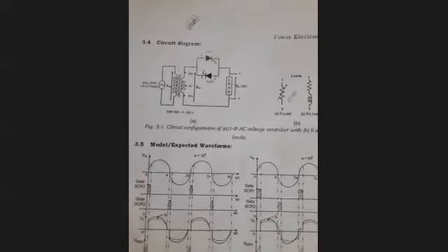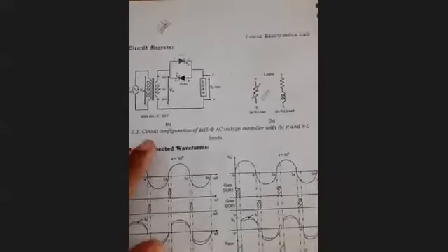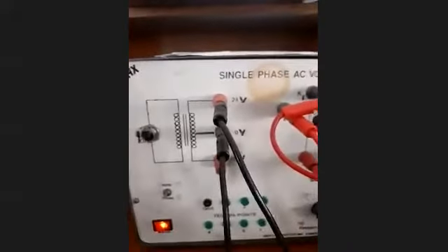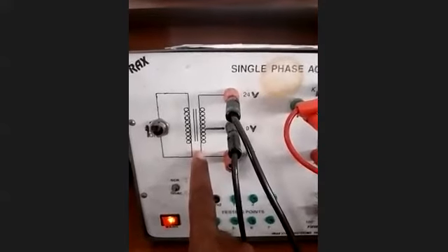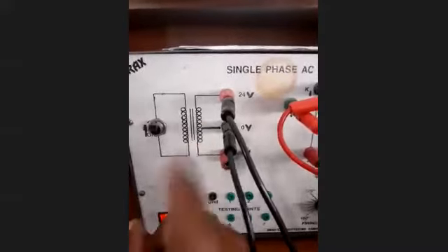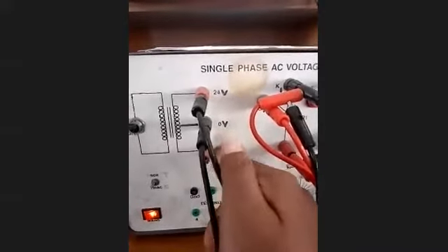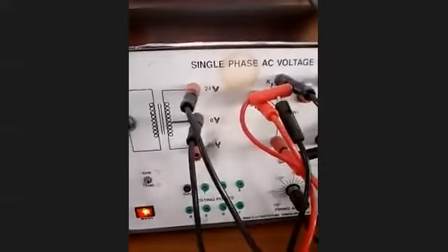But here you can see two thyristors which are connected anti-parallel, and these two thyristors are connected in between the load and source. Now here you can see the same circuit. It is a transformer, it is a step down transformer, and this is also used for isolation purpose, right? So now you can see, if you connect in between these 2 points, you will get 48 volts. You have connected between 0 and 24 means you will get 24 volts across the load.